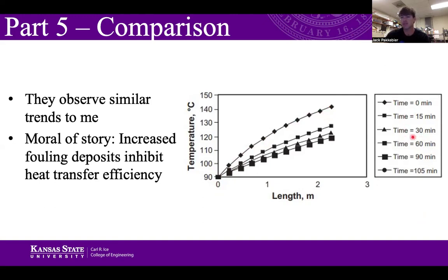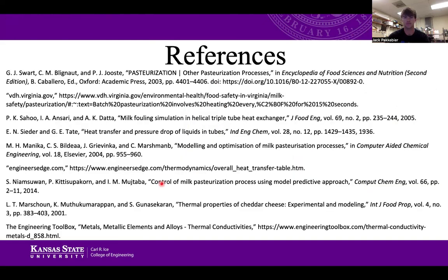But if they neglect cleaning and let it go all the way to hour 40, hour 45, then you can see that their temperature goes significantly lower. Actually, this one's not even depicted on there. So it'd be 90 minutes. They'd only get like 118 compared to their 140 right here. So it again just shows how this fouling is inhibiting heat transfer through the system, increasing the pressure drop, a myriad of undesirable effects.